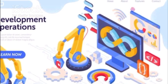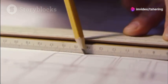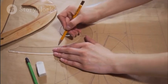Now, let's talk about Ortho Mode. Ortho Mode restricts your cursor movement to horizontal and vertical directions, which is super helpful for drawing straight lines and aligning objects. To toggle ortho mode on or off, just press F8.